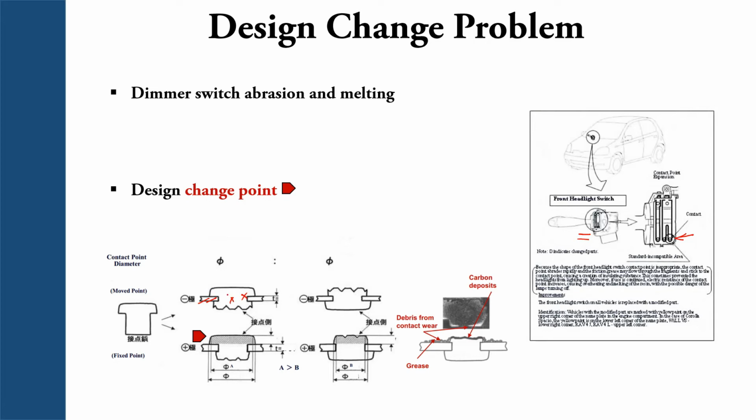So this is the switch and these are the surrounding surfaces, and you can see when you are applying force on that switch to click and unclick, that will cause some kind of interference between the edge of the mating surface and the edges of the main switch. So that will make the switch lose its durability fast.